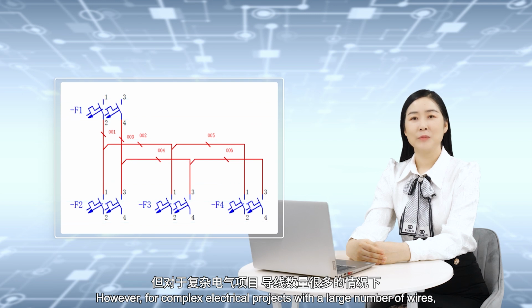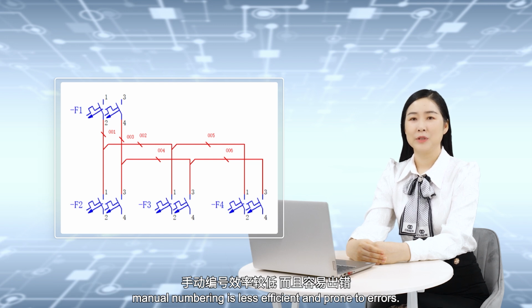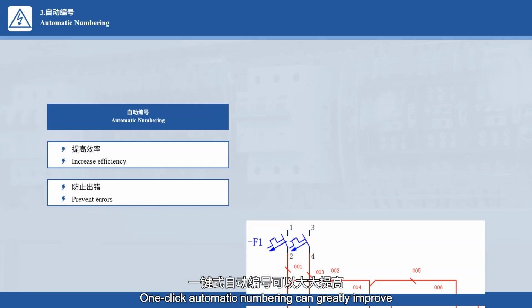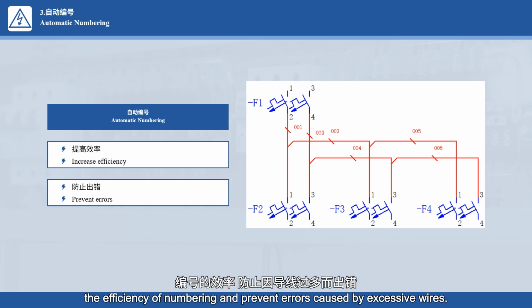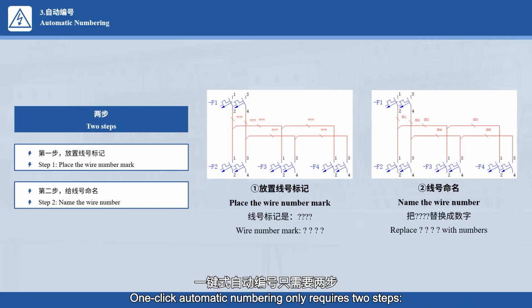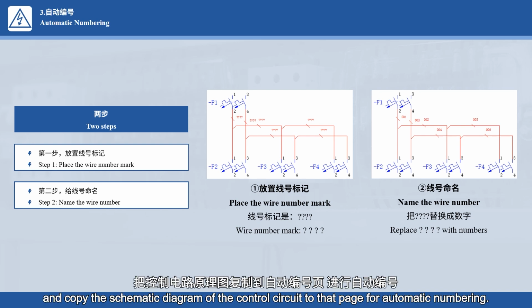However, for complex electrical projects with a large number of wires, manual numbering is less efficient and prone to errors. In such case, we consider using the automatic numbering function. One-click automatic numbering can greatly improve the efficiency of numbering and prevent errors caused by excessive wires. Therefore, in actual generation, we generally choose automatic numbering. One-click automatic numbering only requires two steps. First, place the wire number mark. Second, name the wire number.